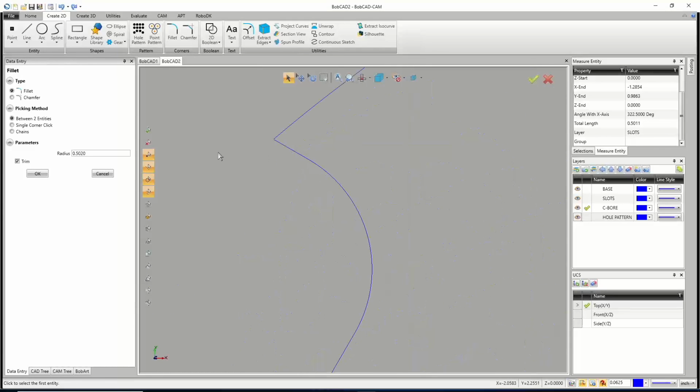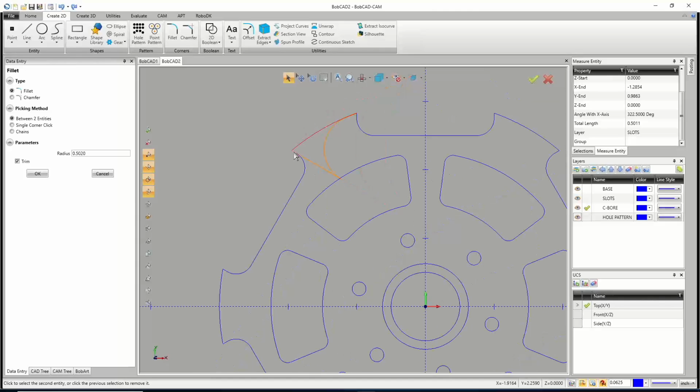And the problem you run into when you're doing sharp ones like this with a big fillet here is that tiny line segment that's there. I can only fillet this if I go to my fillet command. If I was to try, 0.502 is going to be way too large, but if I said, let's fillet between this and this, it'll do that weird, goofy fillet like that. And it's just not right.